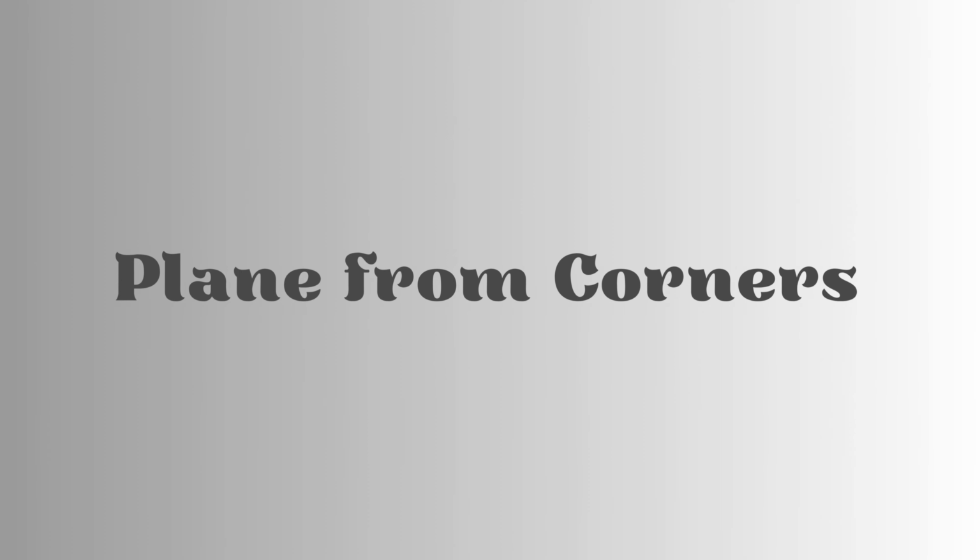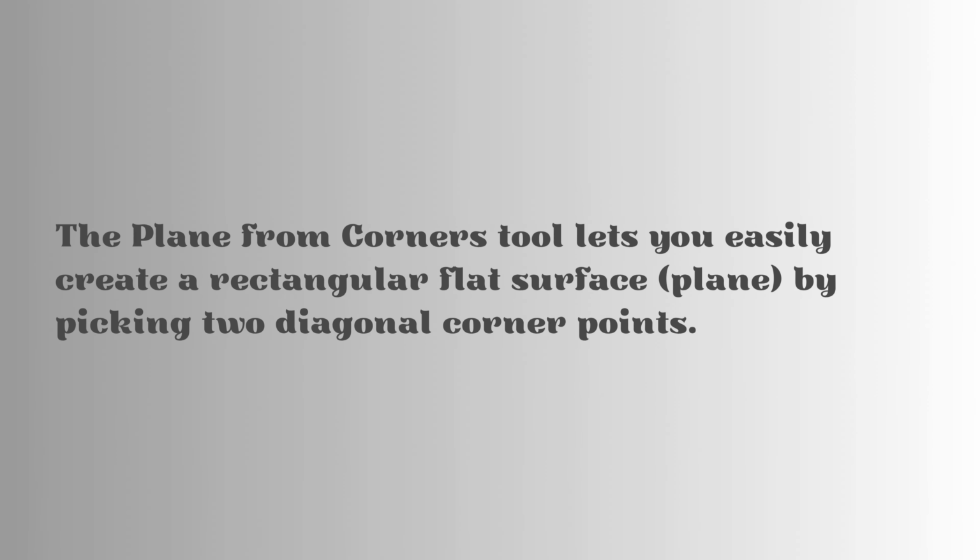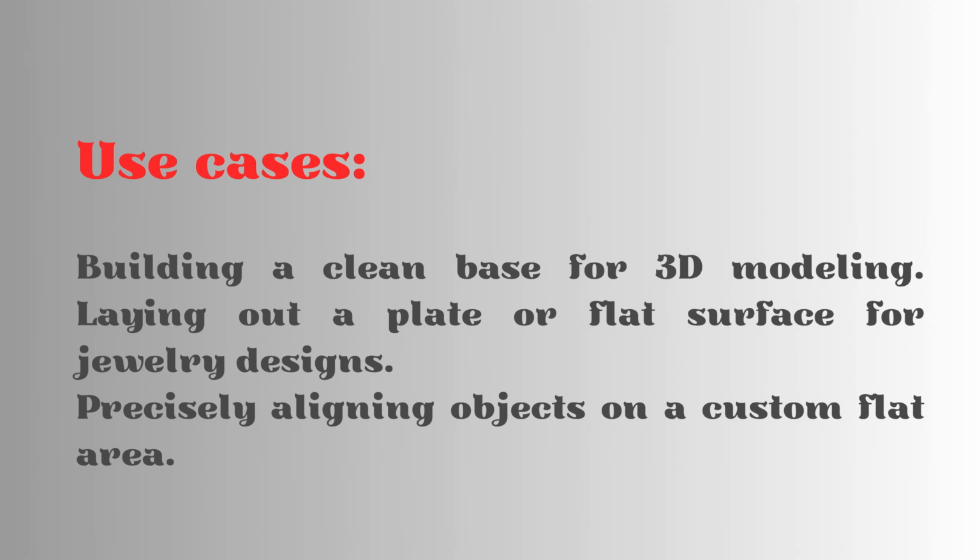Plane from corners. The Plane from Corners tool lets you easily create a rectangular flat surface plane by picking two diagonal corner points, building a clean base for 3D modeling, laying out a plate or flat surface for jewelry designs, precisely aligning objects on a custom flat area.